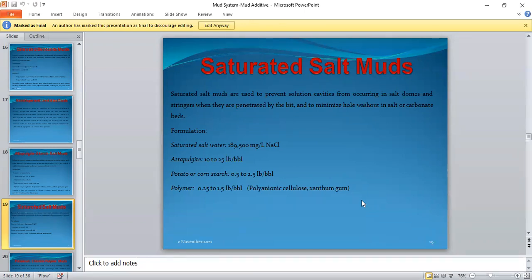So this spud mud, the major function is to clean the hole. You just want to clean the hole because that surface hole, spud mud is used for the surface interval. And the surface interval is not consolidated, it's very porous. It can take water. Your mud loss is more there. Your mud will be entering.